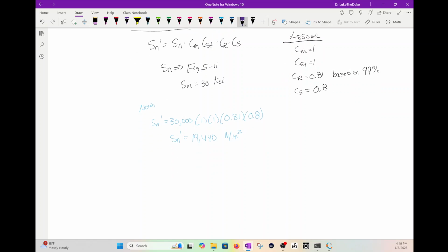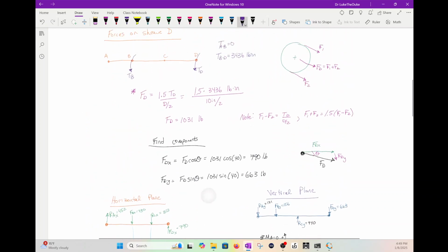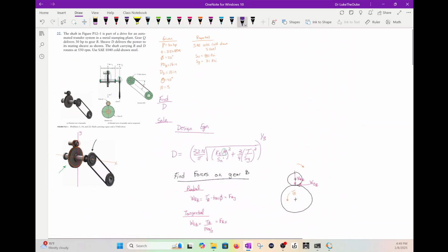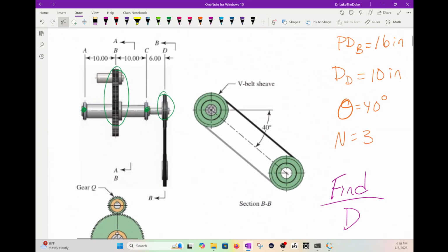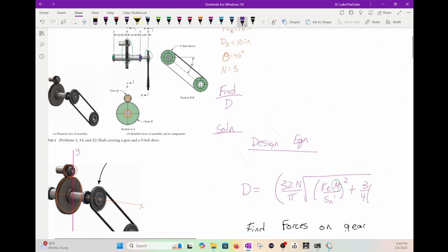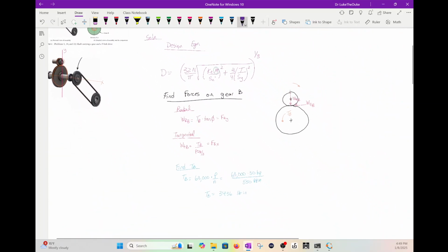And the last thing is KT. And what we're going to do here is we know that there's a torque involved. Go back to this schematic here. Let's zoom in here. So we're looking at this point right here. We know we went from a big diameter to a small one. There's probably some sort of fillet. There's a bearing in there. There's torque. If you go and look at stress concentrations, you'll find a graph.